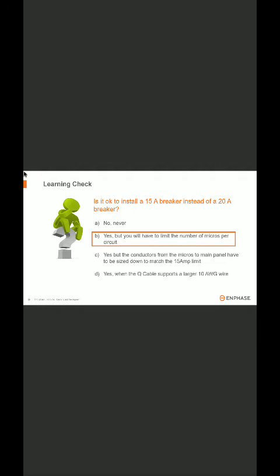So because then your calculation goes down. Then you have to calculate based on 15 amps, and then you have to take care of 25% of precautions, right? So that scenario will be taken care of. So in case it is 15 amps, then what will it be? You're automatically reduced, so you'll be calculating for 11.5 amps. So you'll be dividing 11.5 amps by 1.26.